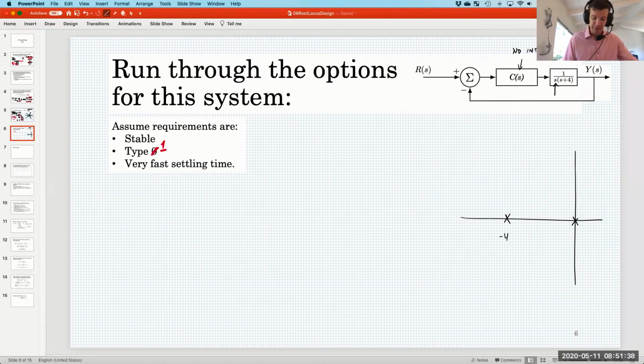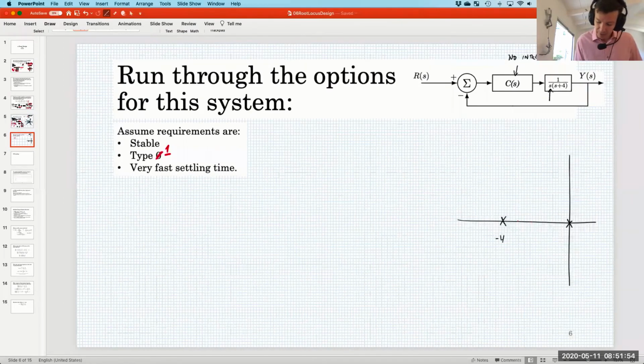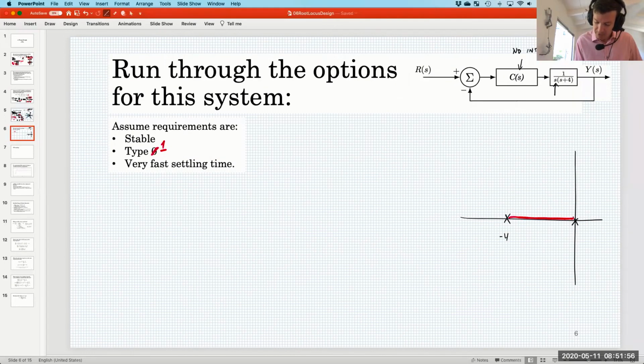If I want the system to be stable, then I think if I were to just do proportional control, that would be pretty good, right? In terms of proportional. So if I had proportional control here, then we would get that, and then we would get that. These are supposed to be vertical. These are always stable. You could throw a dart on a number line, and you would get a gain that would give you a stable system. And it would be type 1 because of the plant integrator.